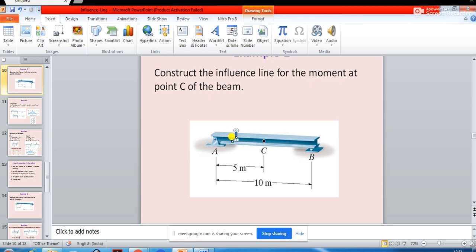See, the equations and other things will remain the same, right? So you see, there is no change actually. If I move this to here, will there be any change? No. Only the limit will change. If this comes over here, there is no change. So the process of finding out influence line diagram for bending moment for a simply supported beam, for any particular position, remains exactly the same whatever the problem may be.